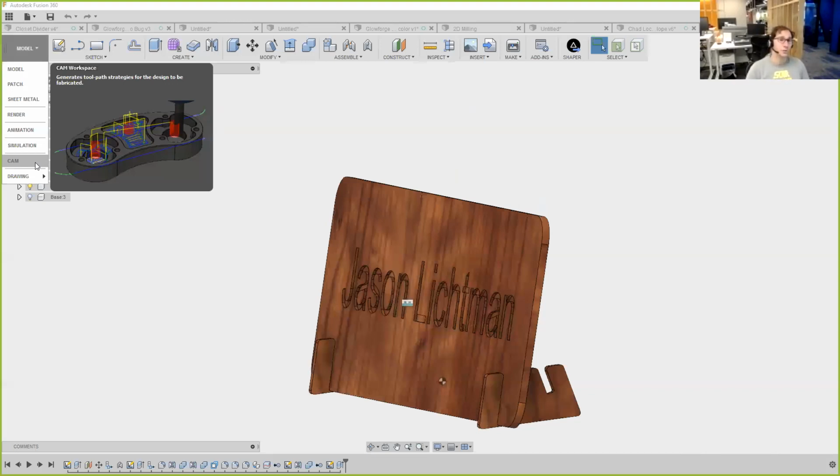The second option was save as DXF, and overall, I really liked it. It is really quick and easy. It will not go straight to the Glowforge app. I do have to bring it into Illustrator and save it as an SVG. Also, there was an issue where if I have 3 different sketches and they're all different shapes and sizes, it doesn't automatically use the same coordinate system for all of them. It actually centers all 3 of those DXFs. And so I didn't really love that.